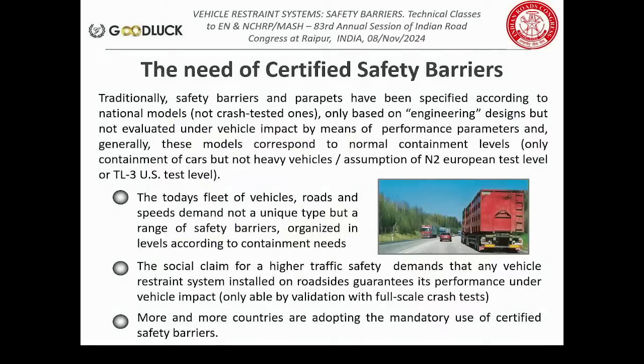Why do we need certified safety barriers on the roads today to address this problem? Traditionally, safety barriers have been used since the 1950s, and they were originally based on engineered design, where the barrier was not evaluated using a full-scale crash test, and that too with very light vehicles. They were not designed to perform for heavy vehicles. The social demand for a higher traffic safety standard requires that any vehicle restraint system installed on the roadside should guarantee its performance, validated with a full-scale crash test.